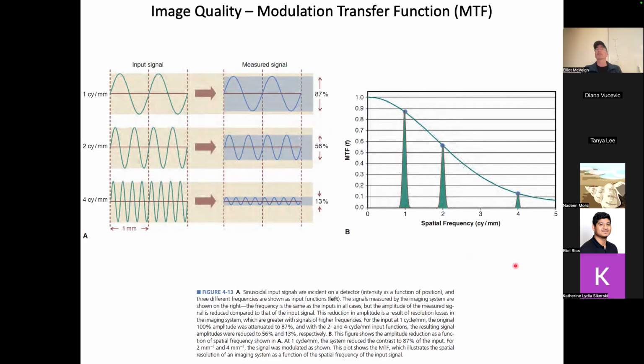And if you look at the spec sheet of a scanner, oftentimes they will tell you what the modulation transfer function is. They'll have measured it and they'll plot it for you. Say, this is our modulation transfer function for this scanner. Sometimes the manufacturer won't show you the whole function. They'll just say, we're down to 10% or 0.1 at this frequency, at 4.3 cycles per millimeter. That's where we're at 0.1. And so they'll just give you that value.